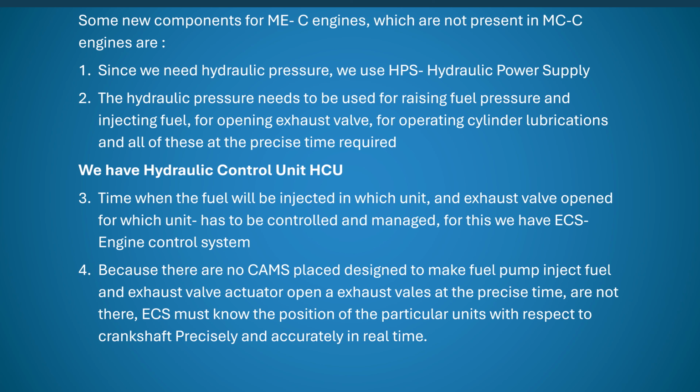We have the hydraulic control unit, HCU, because the hydraulic power you can create. Hydraulic pressure is available, but that has to be put to use. What is the entity which puts that hydraulic pressure to use as per our requirement? It is the hydraulic control unit, HCU. We will see that. The time when the fuel will be injected, in which unit and at what time, and when the exhaust valve is opened, for which unit and at what time, has to be controlled and managed.